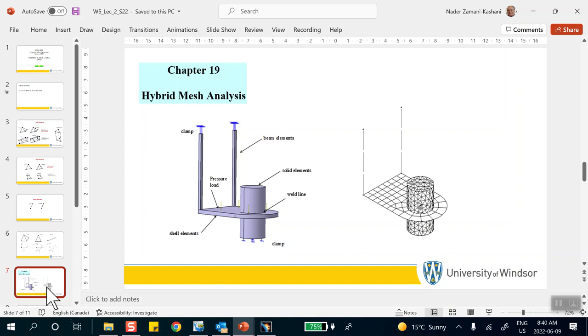See, this is where you saw that guy on the left. Immediately, you should realize that this has to be done as a combination of different elements. When you see something like that, do not jump and make this model with solid elements. Okay? These vertical supports, we're going to do with beam elements. You can see there on the right-hand side, vertical lines.